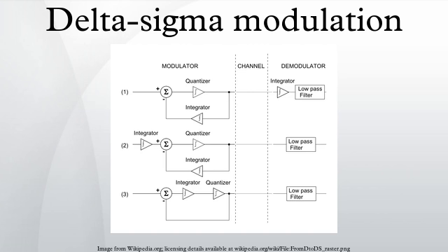In most practical applications the summing interval is large compared with the impulse duration, and for signals which are a significant fraction of full scale the variable separating interval is also small compared with the summing interval. The Nyquist-Shannon sampling theorem requires two samples to render a varying input signal. The samples appropriate to this criterion are two successive delta counts taken in two successive summing intervals. The summing interval, which must accommodate a large count in order to achieve adequate precision, is inevitably long so that the converter can only render relatively low frequencies.